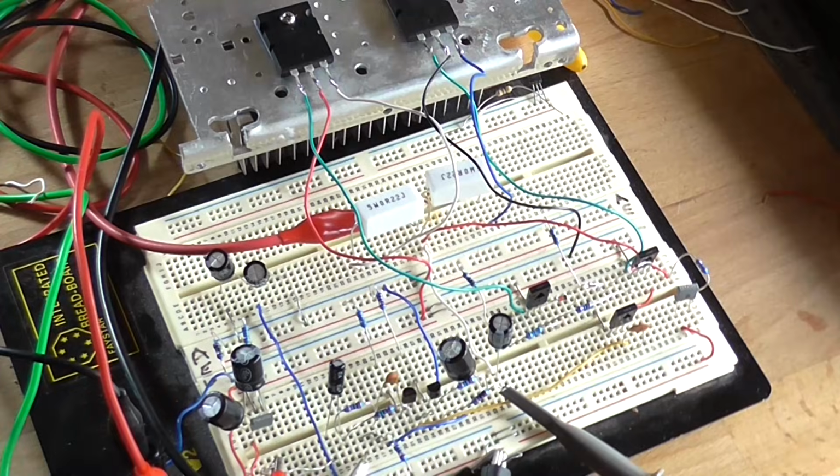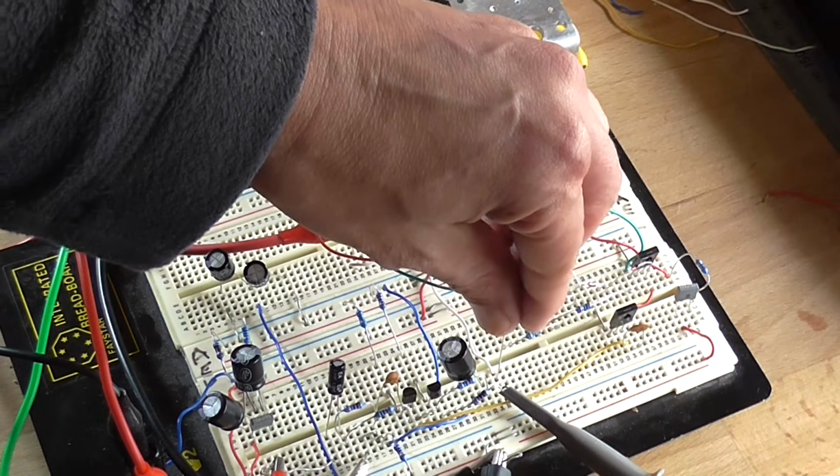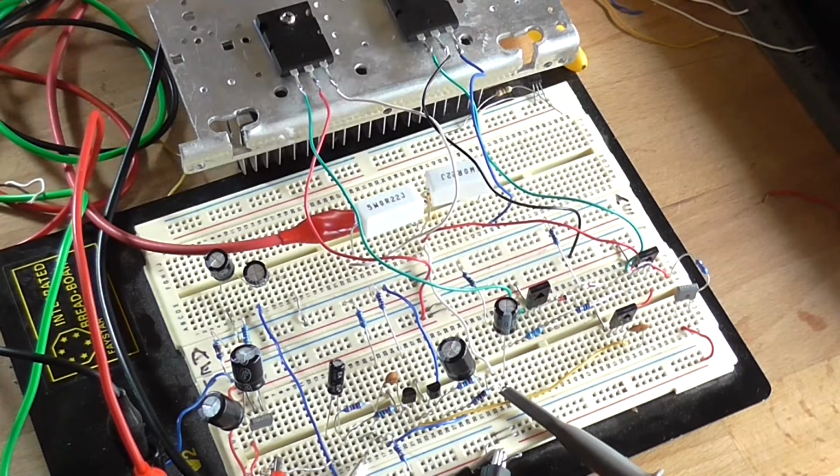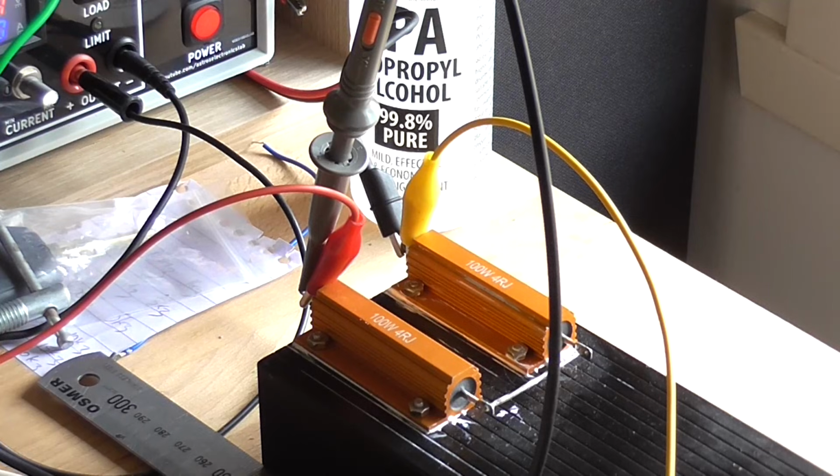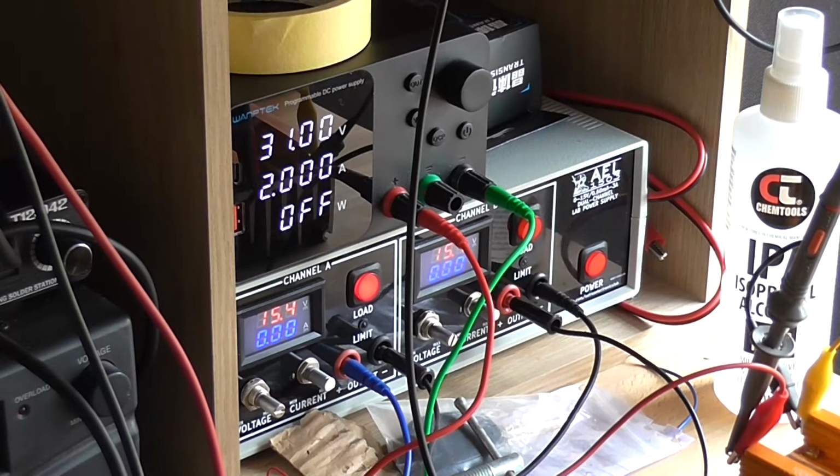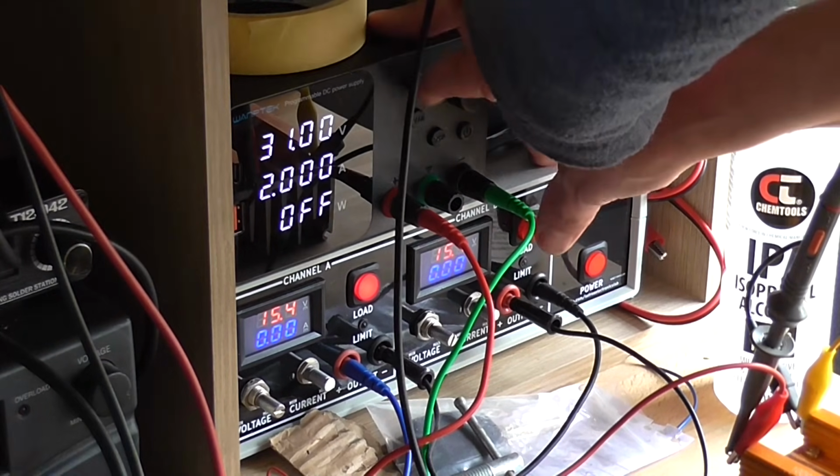So what I'll do is I'll load the thing into an 8 ohm dummy load, and we'll just see how much power it can produce out. I'm going to predict around 35 watts at this power supply rail, which is perfectly fine. And I'll just disconnect the bootstrapping. Okay, we are loaded. Actually, I wish I was loaded in more ways than one. Okay, so I'll turn the supply on.